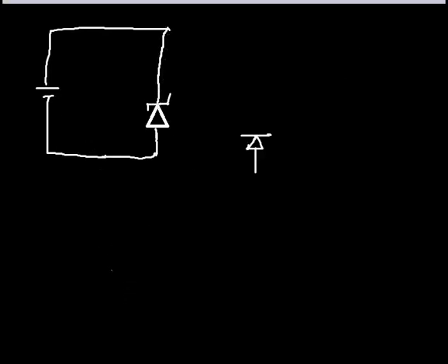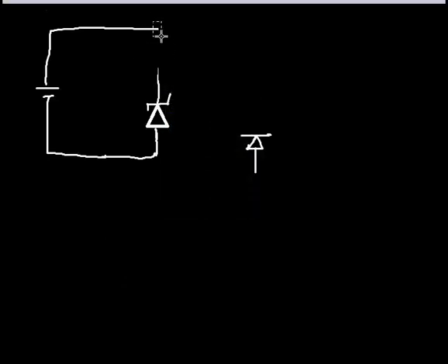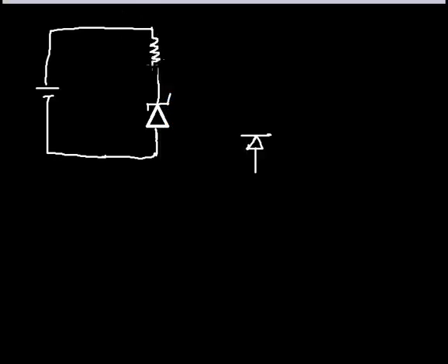Alright, now there is something I could actually connect. Please follow me. I connect a resistor in series to actually limit the current to some extent. Let's say I have a resistance of 500 ohms. Now this Zener diode, look at the characteristic.